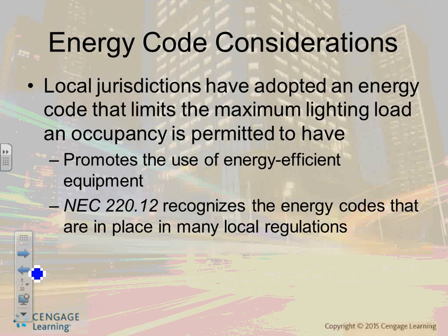You on the feeders only. Future, when we do future expansion, guys, you size the feeders and the services for future expansion. For example, if I have to add another 5,000 square foot on the service, the service has to take into consideration, when you size the service, the conductors, the conduit, and the box have to take into consideration the 5,000 square foot addition. Then you ask yourself, well, how am I going to feed this addition?